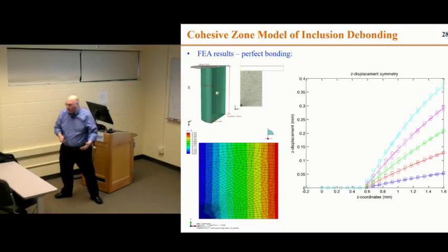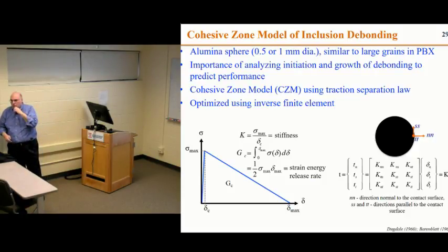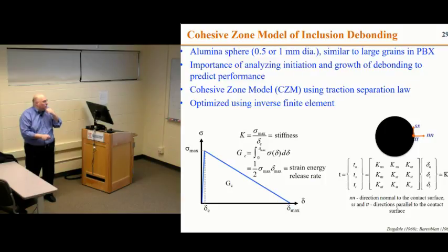We would like them to agree, so we have to somehow model the failure, and we model it with a cohesive failure process, right? We know that the failure is happening at the interface. We're not going to deal with failure in the matrix or the sphere. The only cohesive elements that would be placed would be around the sphere. These would allow softening of this bond between the matrix and the sphere once some critical stress is reached, right? These types of cohesive elements say that failure is not instantaneous where the thing just snaps, but it's a gradual process that takes some time to complete, during which the material is softening or losing resistance as you're increasing the displacement. Then at some point, if these two material points separate far enough, and that's this delta max, then they have no influence on each other, and you have complete failure, right? So traveling along this curve would represent the failure process. Reaching this point would represent the formation of a new crack.